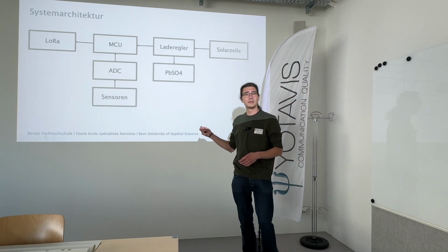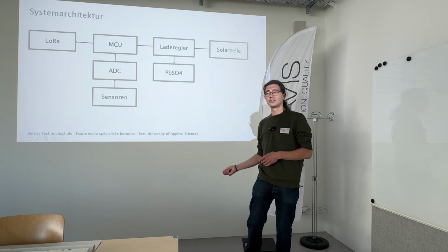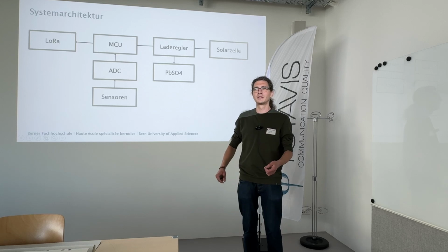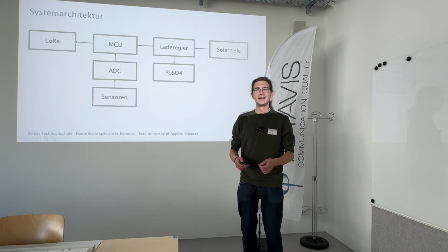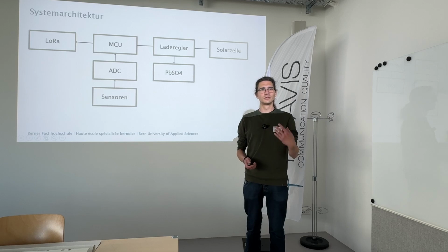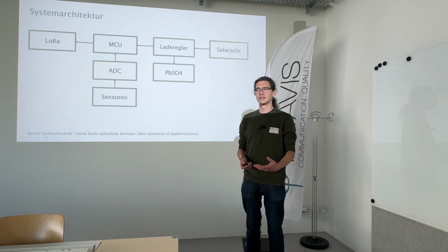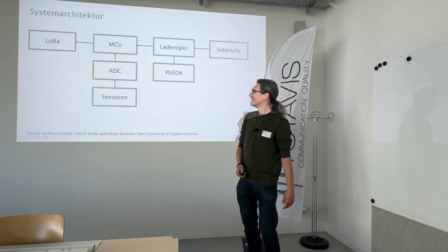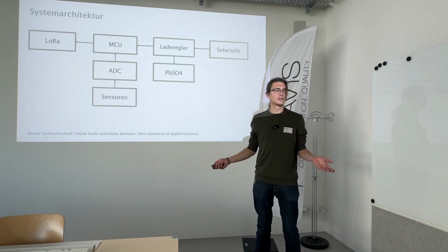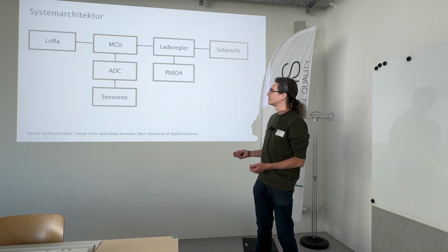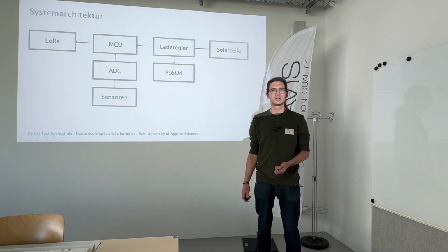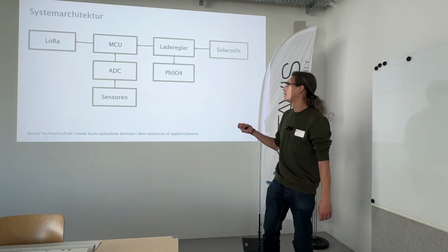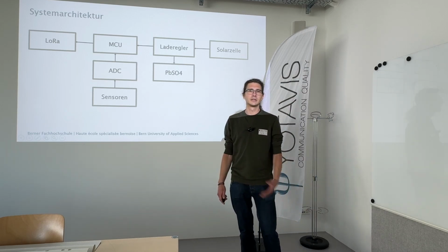And I admit this may sound like a weird choice because it's an outdated technology. But I think most of you may have seen those videos of cell phone lithium polymer batteries going up in flames in people's pockets. And this is certainly not something that we would like to introduce into a forest during a drought period, where the fire hazard from the forest side is already high. We don't want to add to that. And the other thing is, since we are out in nature, it can get cold, and most of the lithium-based batteries don't really like to be charged in sub-zero temperatures. There are special ones, I know. So we really went for lead acid because it's robust technology and they're very hard to kill.